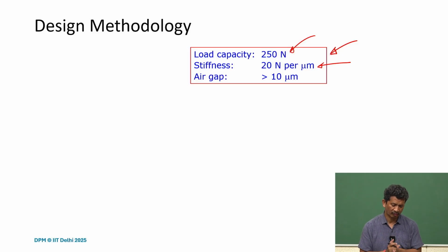So you can see that the stiffness value is very high, and of course the air gap also depends on the manufacturing limitations, what kind of surfaces we can get. So let's not stretch ourselves too much and try to be within a limit. Suppose, let's say, an air gap of the order of 10 micron may be better. So yeah, we say okay, 10 micron.